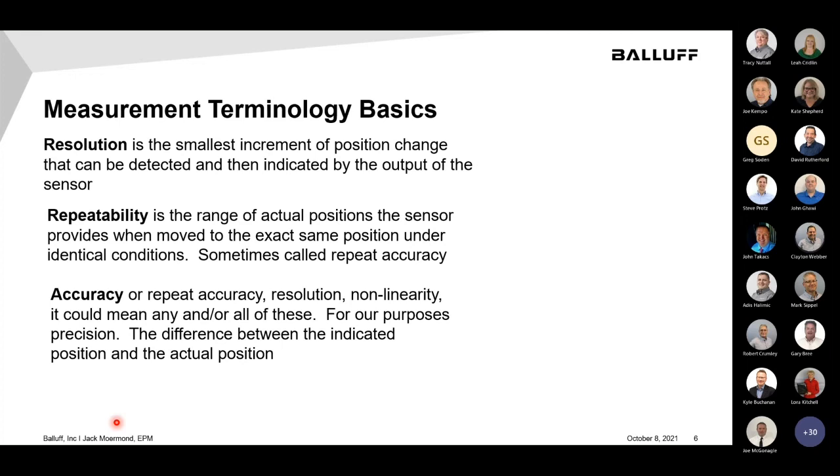Then we get into accuracy, and this is what a lot of folks refer to. Some customers will say, hey, I need the accuracy of 1 micron. Well, basically, that's resolution. So accuracy sometimes can be referred to, some customers might refer to accuracy as resolution or nonlinearity. Could be any or all of those. For our purposes, we look at the precision. Okay, so what is the actual position that you're seeing?